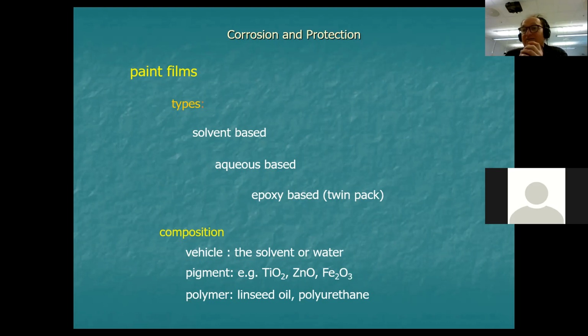And it might also, and very often does, contain ferric oxide, especially if the paint is red in color. And this is often used as a primer on steel for obvious reasons. Ferric oxide is in effect rust. And if you put that into the paint in this way, you can actually protect the underlying steel by putting the rust there beforehand in a very controlled way. And therefore we use ferric oxide for this purpose, and it works very well, it has to be said.